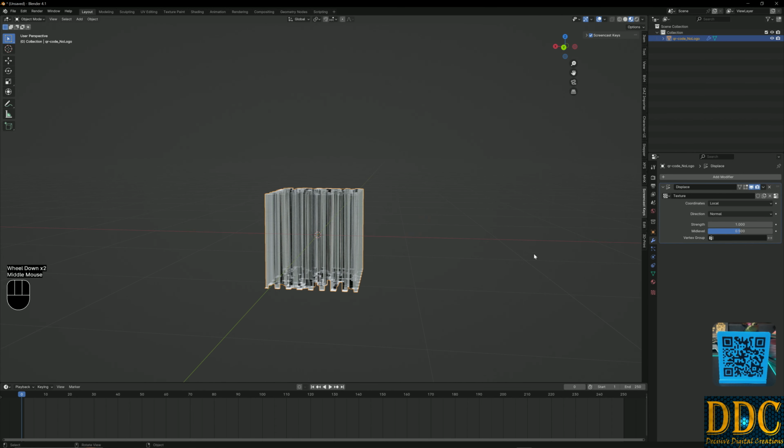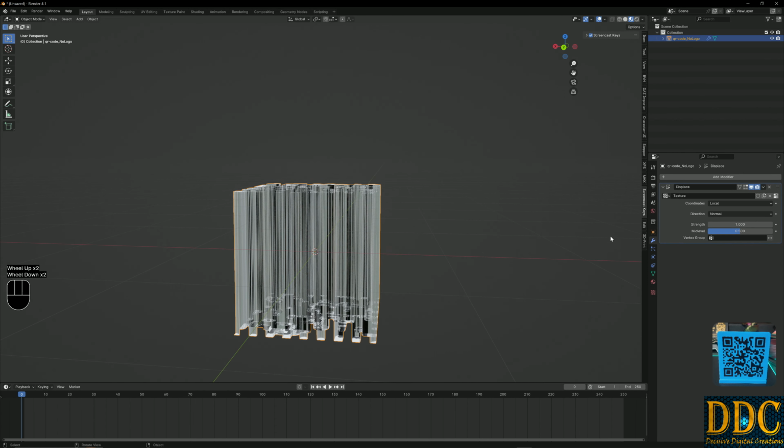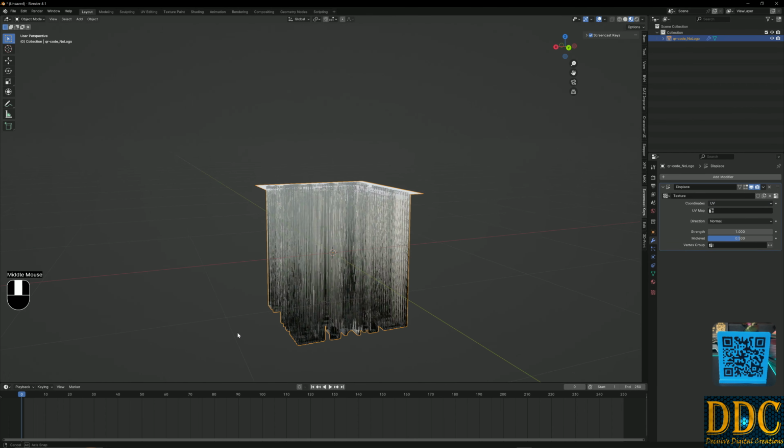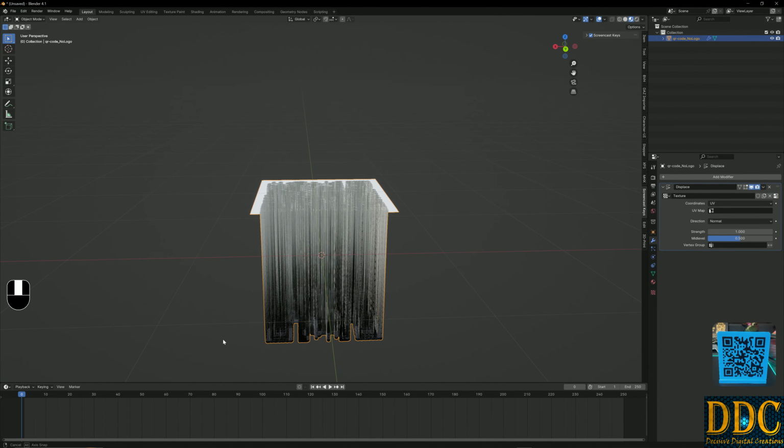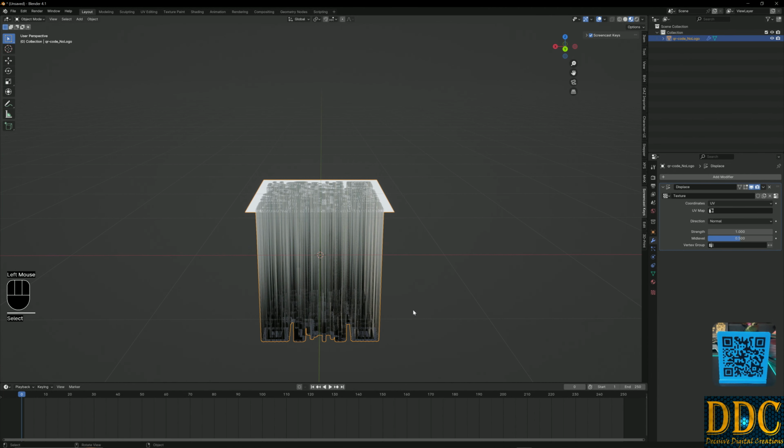But we've got an issue. It's displaced a lot, for one. So let's change this to UV. Okay, now notice how it tightened up. Alright. Now, we've got one other issue here. Right now we're extruding or displacing the image out the bottom instead of the top. Notice my axis, Z is up and Z negative is down.